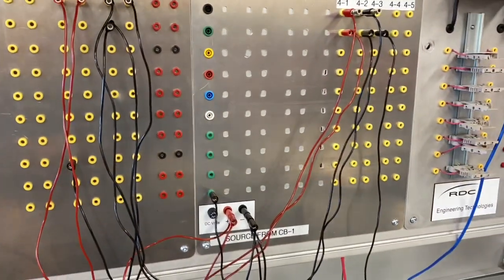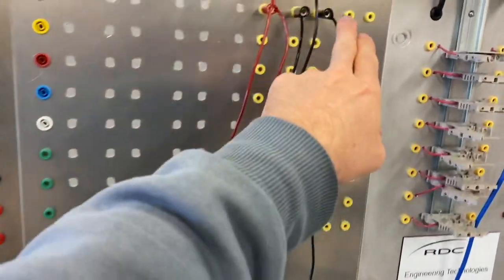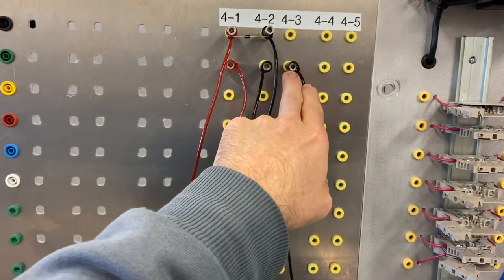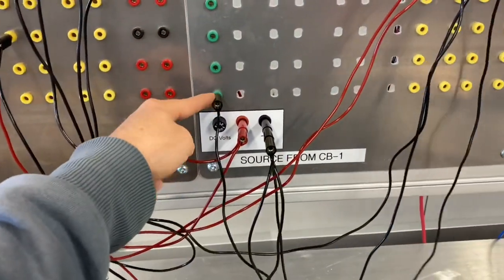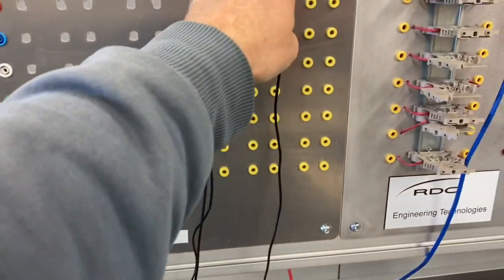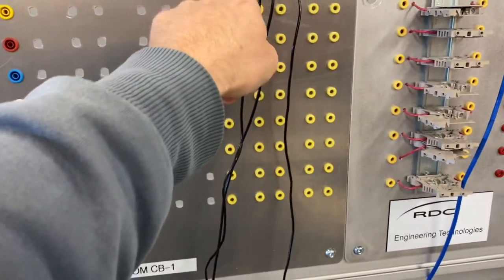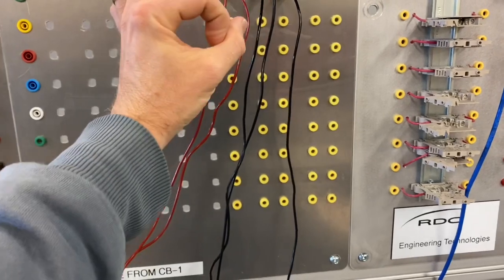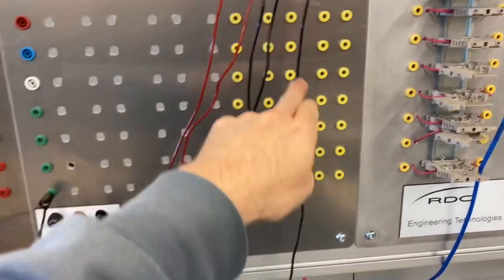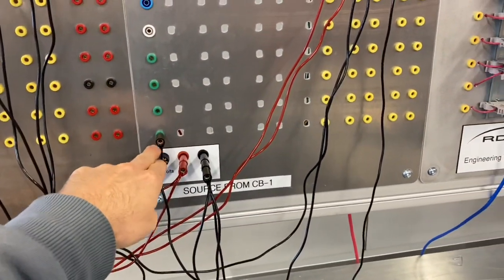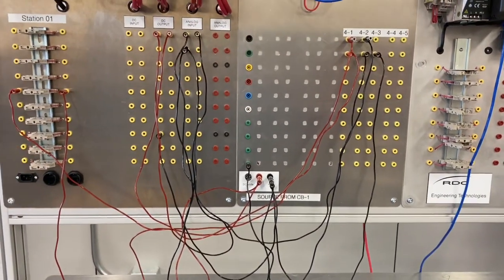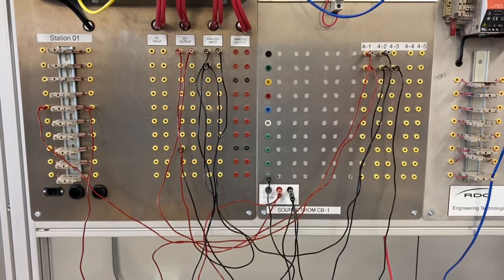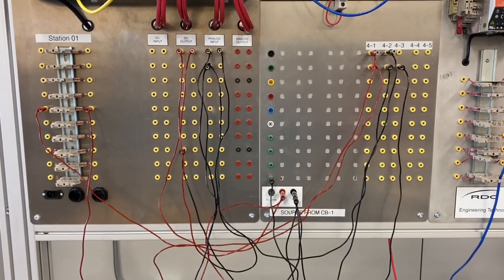So I'm gonna have you look up what that is in the manual. And the other thing I was going to point out, I have this 3rd wire that I didn't talk about going out to the transmitter, and I've got this connected over to ground here. The reason for that is we got a twisted pair cable going out, it's got a shield on it and a drain wire. This is going to drain any interference to ground. That's what that is there for. So I just want to point out those 2 things as well. Those are important to know when we're dealing with PLCs. Proper wiring practices.